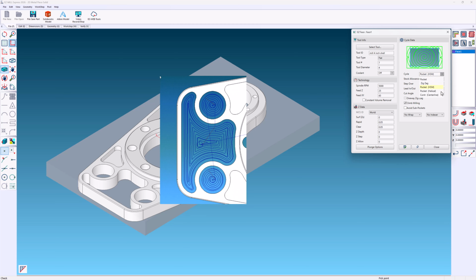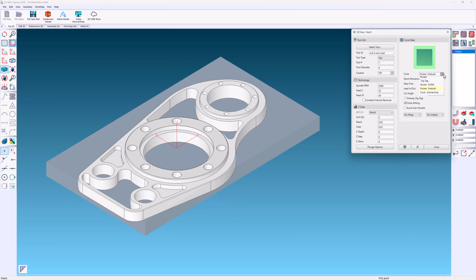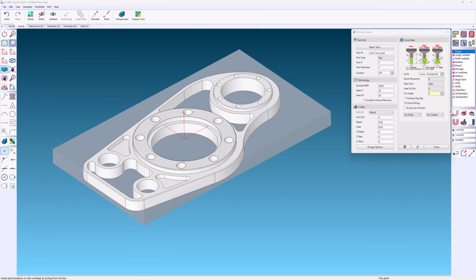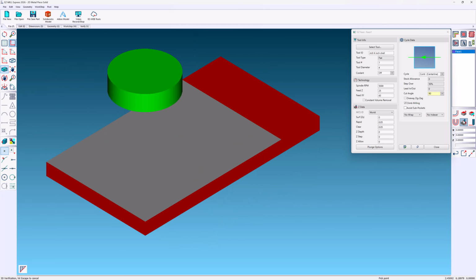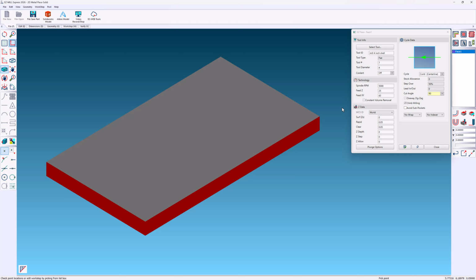Helical can be looked at like the yellow brick road. It's a continuous spiral until it reaches the end where the entire perimeter is cut. Centerline positions the cutter on center of the selected surfaces along the length or width. If the cutter is large enough, CAD-CAM generates a single pass. If the cutter is not large enough, CAD-CAM adds the necessary passes to complete the job. With our new version, you can verify to calculate and visualize the toolpath while the operation is open.